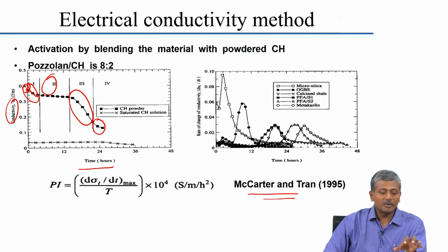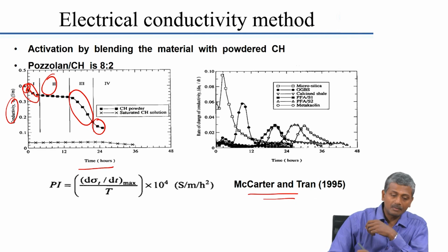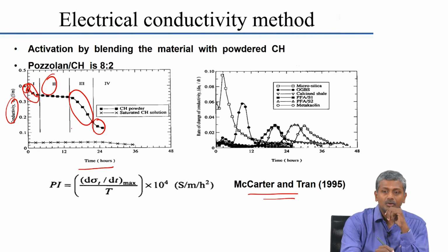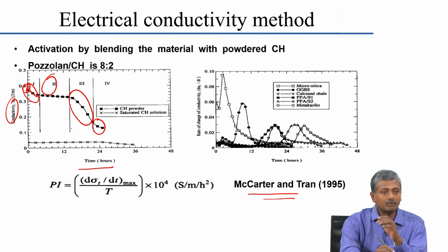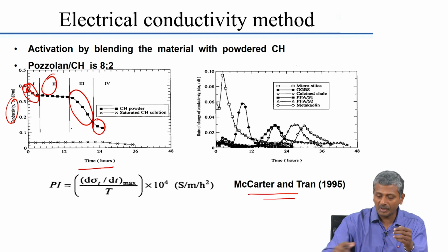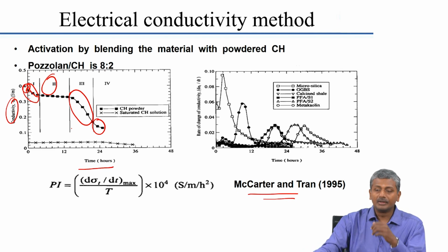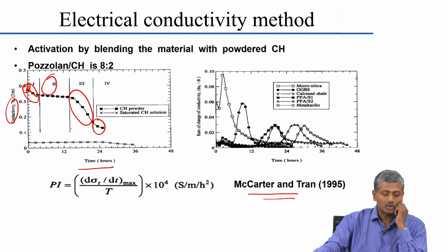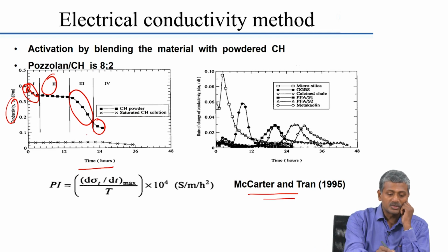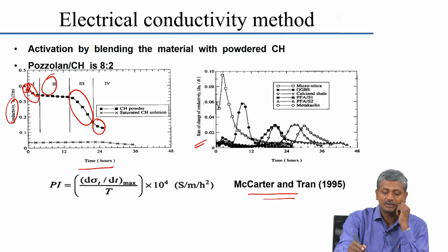So, what people have been able to do is such systems have been able to depict much better the kind of pozzolanic activity that may be there for your systems. Secondly, they have also been able to relate conductivity measurements to the setting time of the concrete fairly accurately. There are several papers on this, you can read this paper, or there are additional papers also available which talk about this aspect.